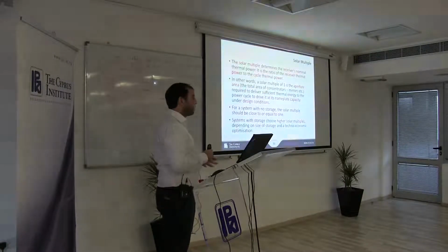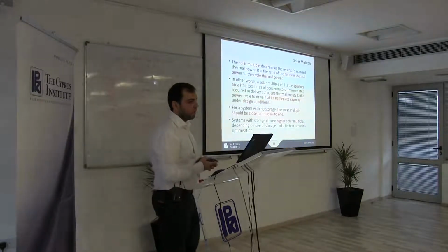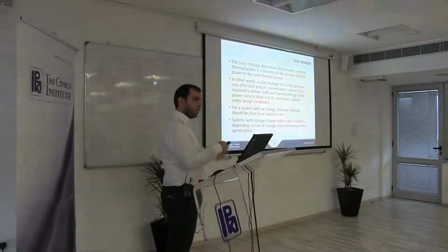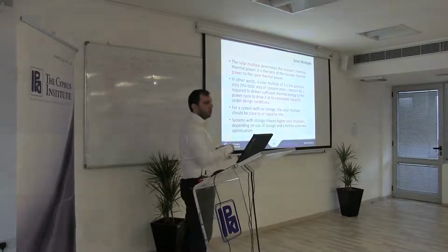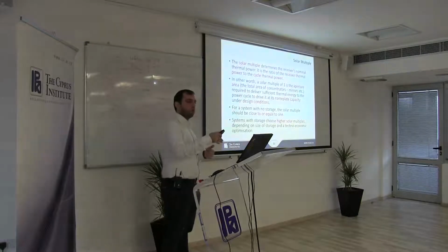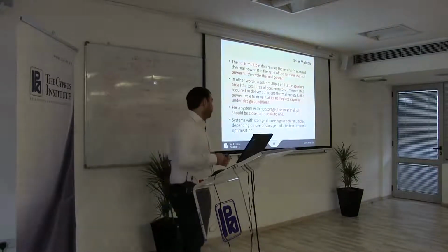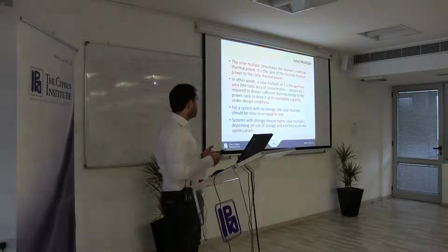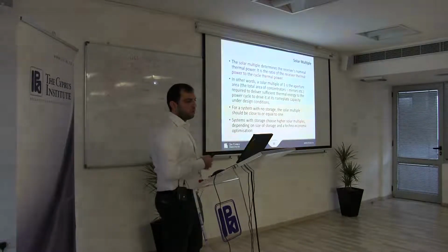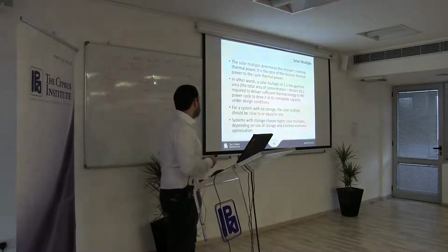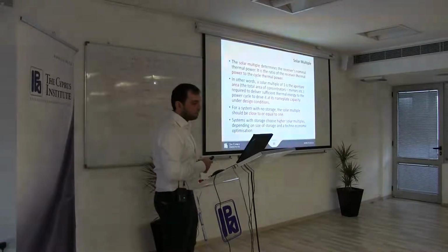But in systems with storage, we can choose higher solar multiples, because we can store the thermal energy and then drive the power cycle for a longer amount of time, and not only when there is sun available. And the size of this solar multiple is basically determined through techno-economic optimization. And this also determines the size of storage, of course.